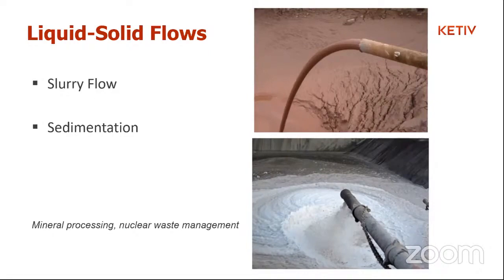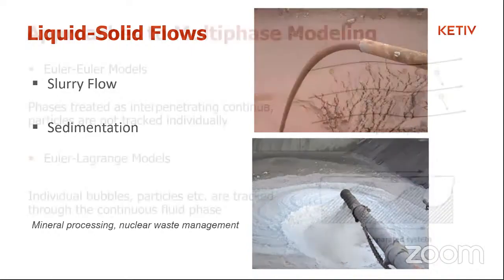It depends a lot on your solid particle properties how the flow behaves over time. In sedimentation, as the name suggests, you'll have uniformly dispersed solid particles that eventually settle down at the bottom of the container over a period of time. Then you have a clear demarcation between the solid phase and the liquid phase after some time has passed. So these are all the different classifications of the flows that you might be interested in. And depending on which type of flow you're modeling, you might have to choose different approaches in your CFD solver.